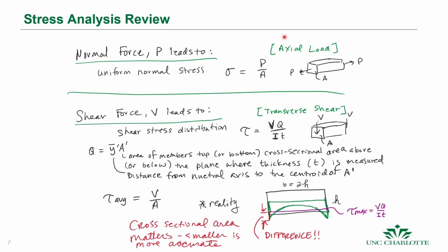And so we have our axial loads, which is just our axial load over the area. We know that. The stresses right at the load are not equally distributed, but because of St. Venant's principle, some distance below that material, the stresses are uniform enough for us to consider this simplified version for axial loading. We have shear force in materials.